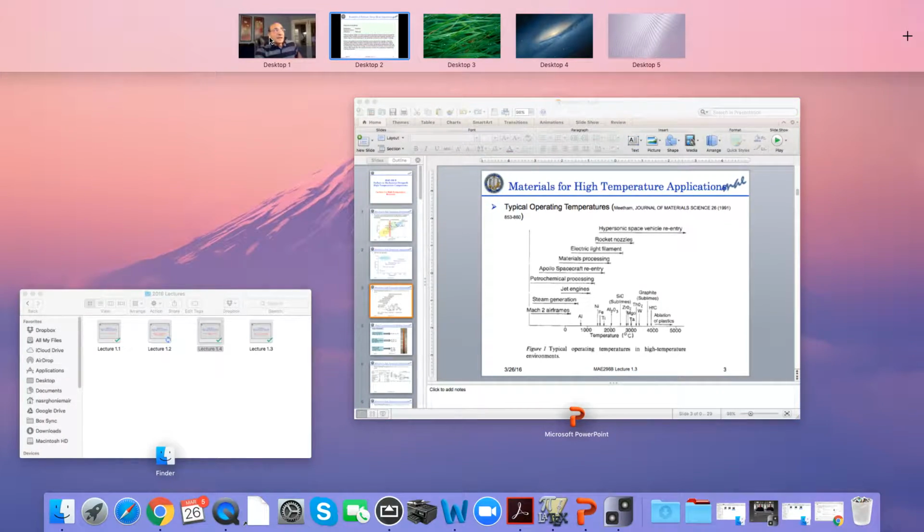The palladium group is interesting because palladium has high chemical catalyst ability, so it wants to work with the gases and enhance the gas exchange and the reactions on the surface. Same thing for iridium and so forth. But although it enhances the catalyst, it itself does not oxidize. So that makes it ideal for catalytic converters, for example, or for coatings in rocket engines